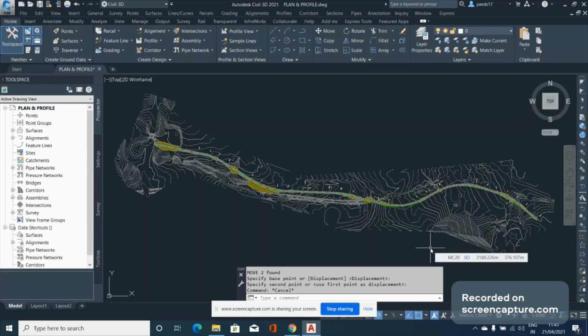This is also a benefit: you don't need to open each and every individual drawing just to change the date or the revision number. You can do it using the DST file, and it happens in all the files. This is an advantage and can save you a lot of time, which is why you need to use the Plan Production tools.